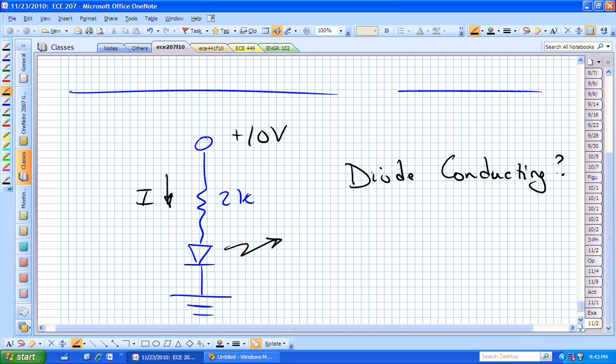And what's the circuit? You may feel very uncomfortable with this diagram. Somebody just labeled that node as 10 volts. Well, what they're really saying is the following. They've now put this, which is implied, that they have a source. And now we have current flowing in this mesh. That's the implied concept. Now can you do the analysis?